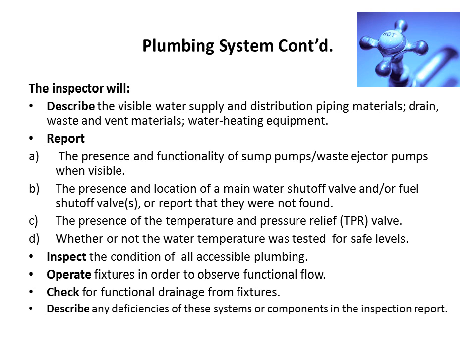Inspect the condition of all accessible plumbing. Operate fixtures in order to observe functional flow. Check for functional drainage from fixtures. And describe any deficiencies of these systems or components in the inspection report.